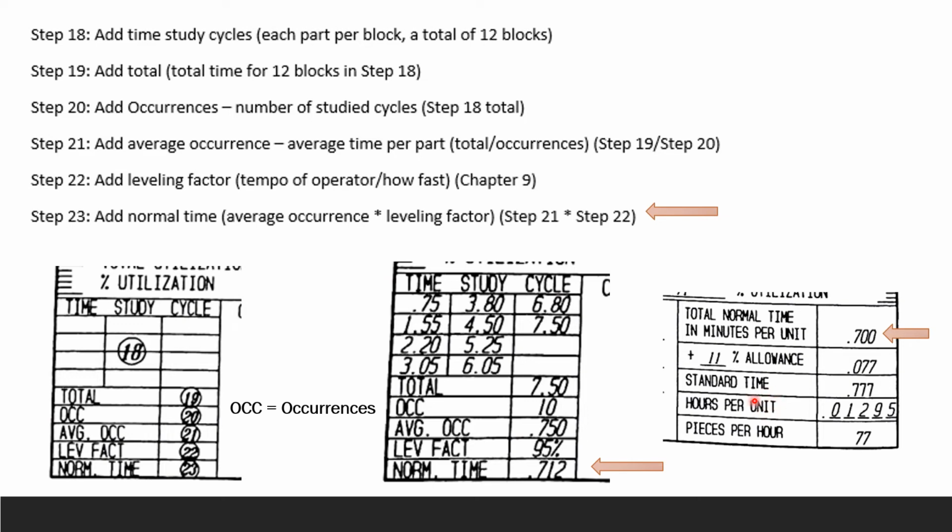So every time you produce or operate a unit, you're gonna get the time for that by measuring the time for it, and that usually comes in minutes. So you're gonna change that minutes by dividing with your 60 minutes per hour, okay? And you will get minutes into hours, and then we will get your hours per unit right there. So that I explained in chapters 3 and 4. Okay, so that goes into the